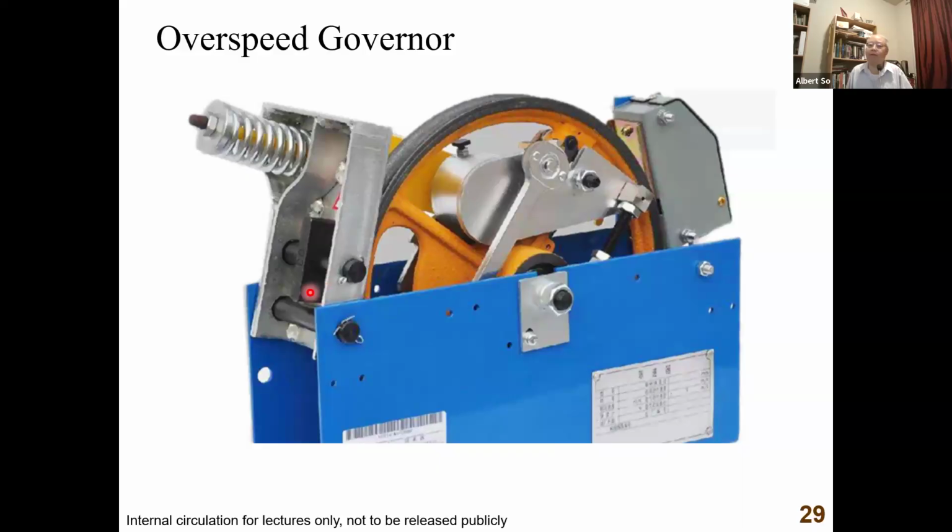Right. Now the purpose of this sheave is, you can see here, the fly weight. This is a fly weight. Now when the car is moving under rated speed, safe speed, okay, rated speed or the normal speed, nothing happens. But if the car is moving downward at very high speed, then this fly weight will, because of the centripetal force or centrifugal force, try to go outward.